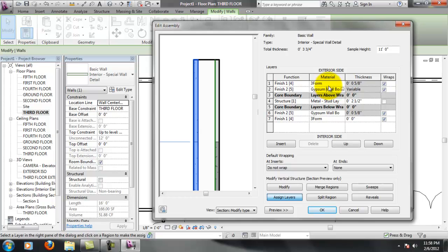I've got that on the wrong side. Notice if I select this wall, this side selects. So this freeform needs to be on this side over here. So I'll just select the freeform again and then select that. And I'll go over to the other gypsum board and then the other freeform and select that. So there, I have freeform there, gypsum there, metal stud in the middle, gypsum, and freeform. So you want to make sure these are all in line where they need to be.